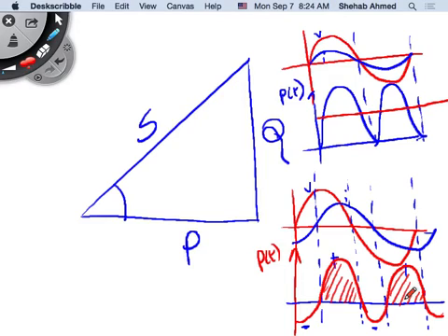If that power is negative, then it's generating that power, giving it back to the source. Right? So that's what happens when you have a phase shift between this voltage and current, or what we call a power factor angle between the voltage and current. Right? And this exchange of power between the source and the load, does it contribute to the average value?